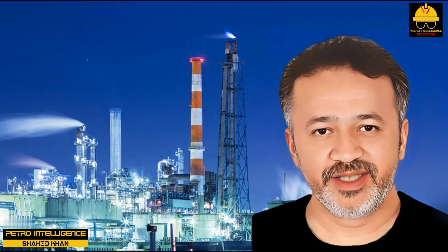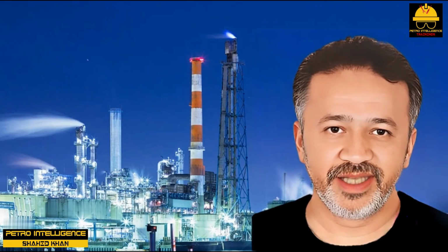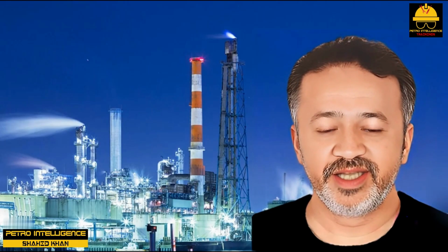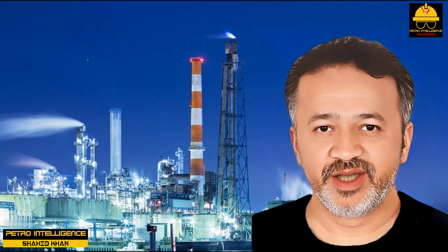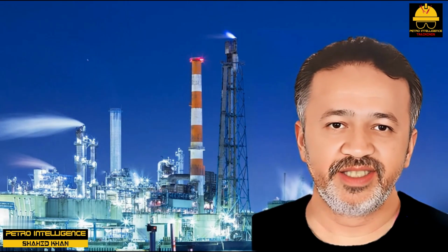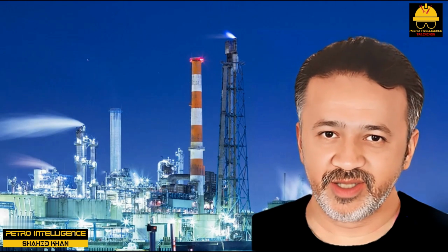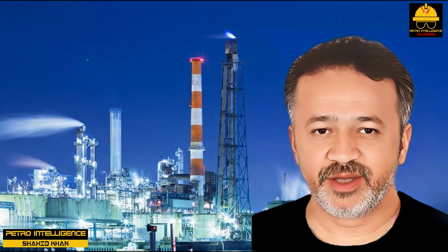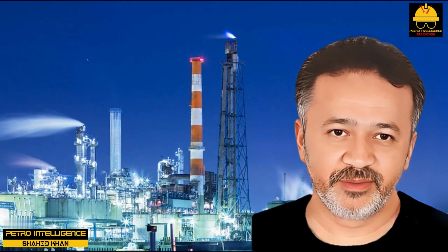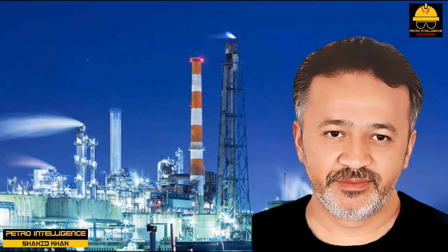He found that capacity was limited to 18,000 BSD by the refrigerant circulation rate. He had plenty of compressor capacity, but as he increased the turbine speed to run his compressor faster and circulate more isobutane refrigerant, the compressor's suction pressure declined to 1 psig. Running the compressor suction below atmospheric pressure is possible, but dangerous.